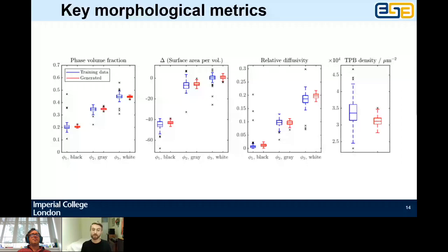One of the things we can do is force our generated data to have periodic microstructure. Okay, so if a particle comes off on the right-hand side of the volume, that same particle re-emerges on the left-hand side of the volume. Same with top and bottom and left and right, front and back. Okay, why is that helpful? If you would like to simulate a volume of battery structure, these microstructures are hierarchical.